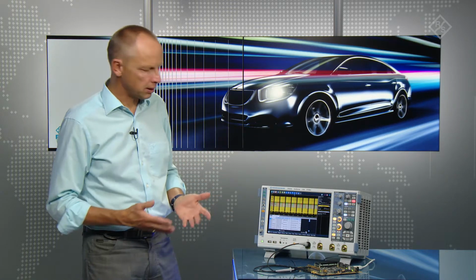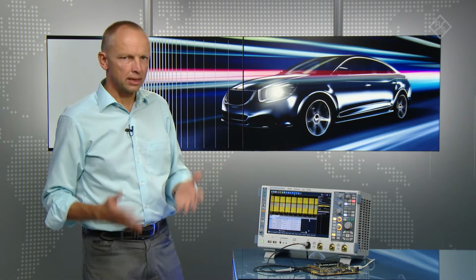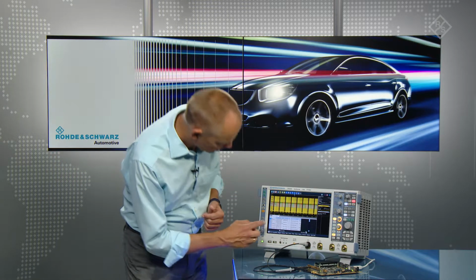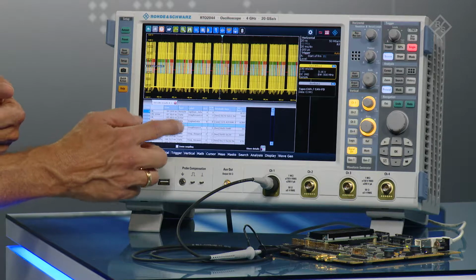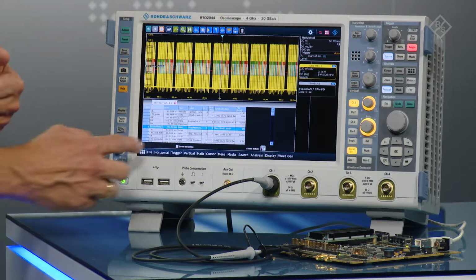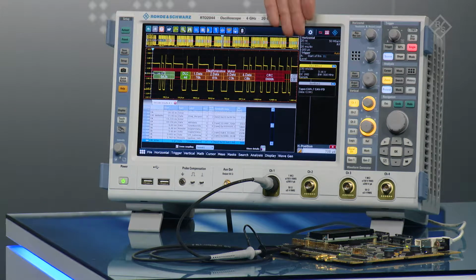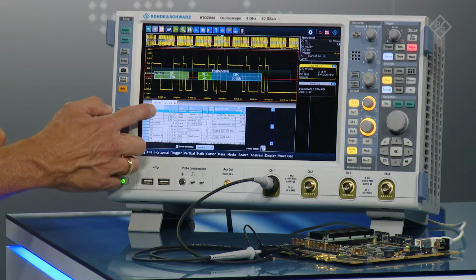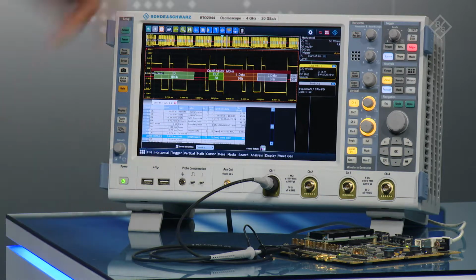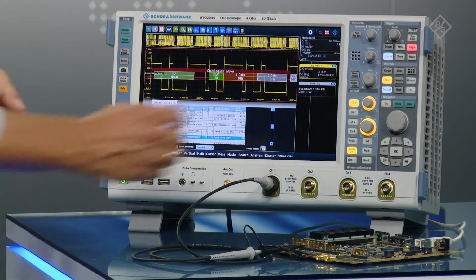The simplest way is to take that capture and look into the details of that error. So when we look into the bit stuffing error, for example, we can activate the zoom coupling. When you do that, you jump directly with a zoom to that error frame that we have here, the CRC error or the bit stuffing error. So here you see the error frame that was causing the bit stuffing error.